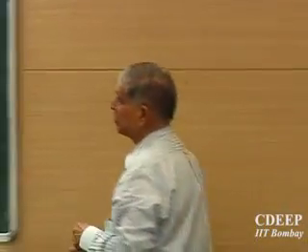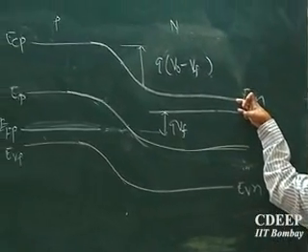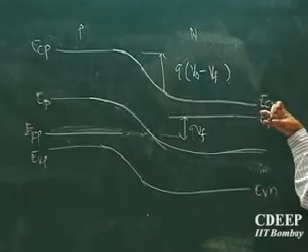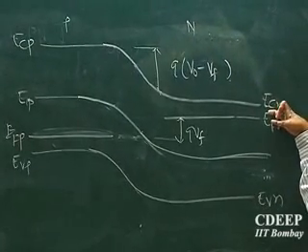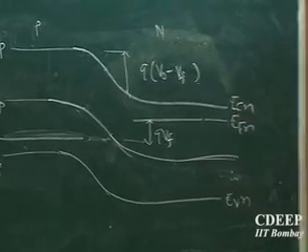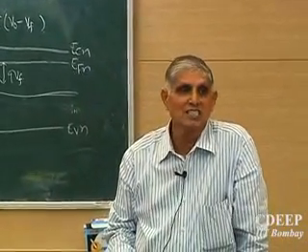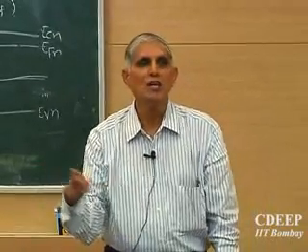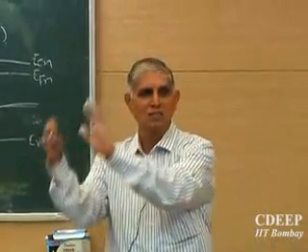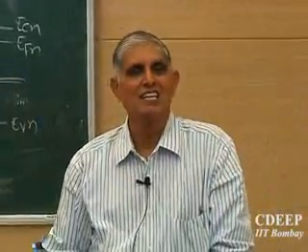This is very interesting. If that is so, once I know the position of Fermi levels, I can find the relationship of n, earlier in thermal equilibrium and after the split. The carrier concentrations I can now relate from this band diagram. Once I know they have changed, I will be able to use statistics. Which statistics do you want to use? Boltzmann, because I said this is my assumption. On the N side and the P side together I may not be correct, but as far as each side is concerned it is steady state.